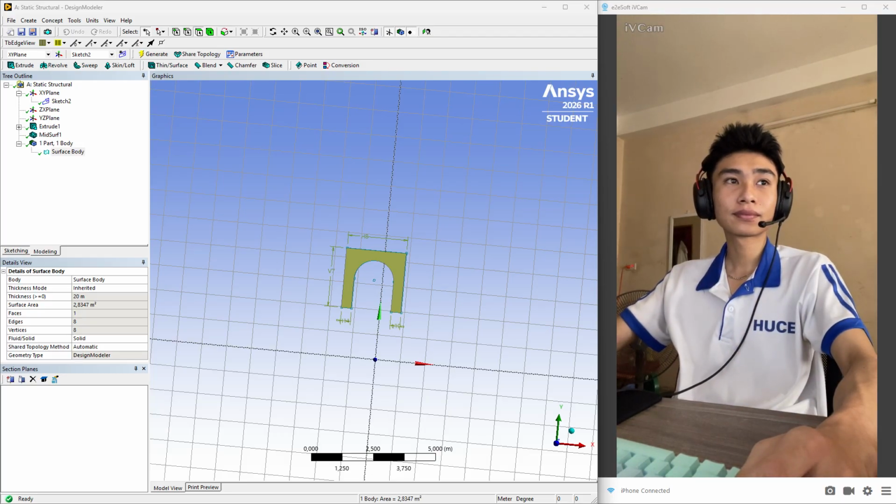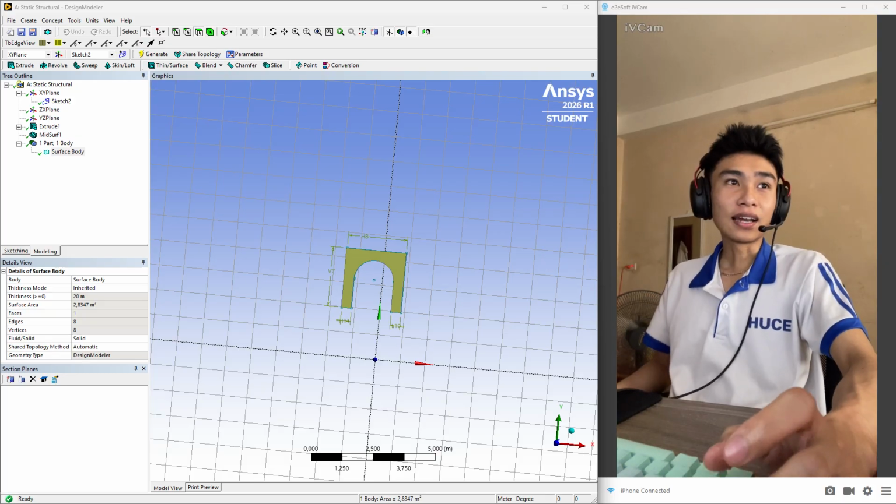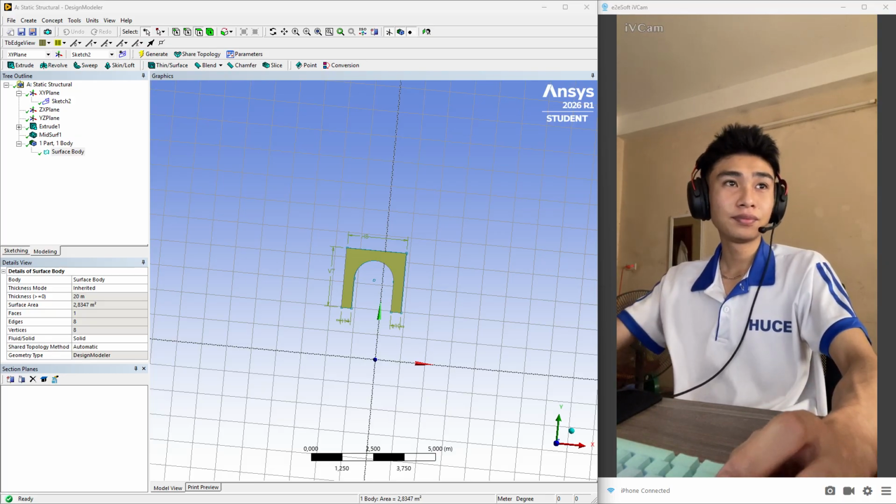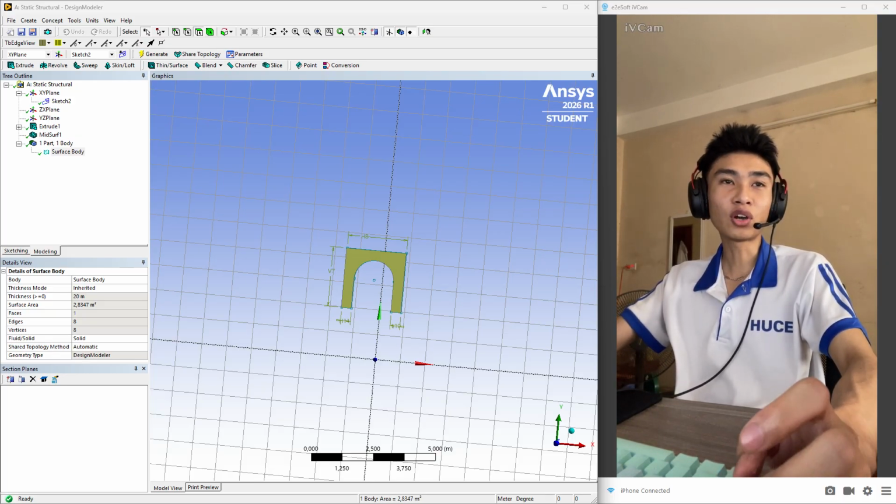perform the calculation on this surface body, we are using 2D elements. So 2D elements have only two dimensions, there will be no third dimension like tetrahedron element or hexagonal element. Here we are using quad 4 or tri 3 element. Ok. Now we'll move to the ANSYS Mechanical.